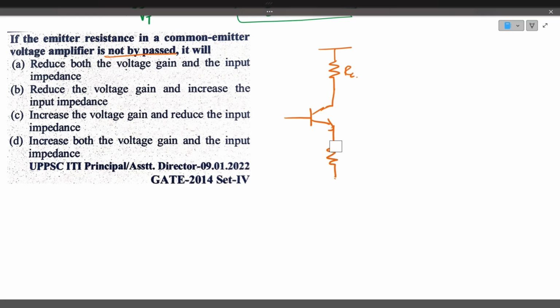Here we have got two resistances, emitter model resistance, which is very small resistance, and emitter resistance. This is the base where input is given. Okay. So here the common emitter he told, so output is collected at the collector. This is without bypassing. With bypassing we'll see.